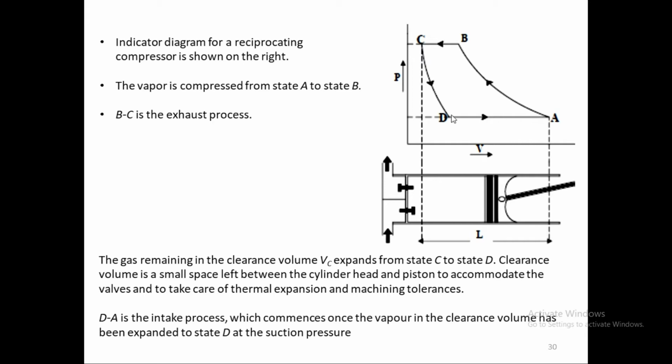So the actual volume of the gas being compressed and the volume of the fresh gas which has been taken in are different. It is not the same as the swept volume, because the swept volume must include some portion which was the trapped gas which is expanded. So that's the difference between the swept volume and the actual compressed volume.